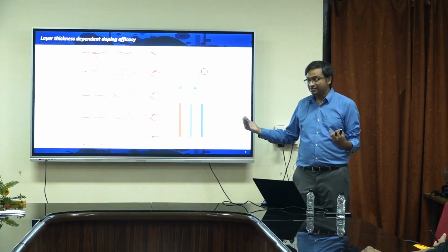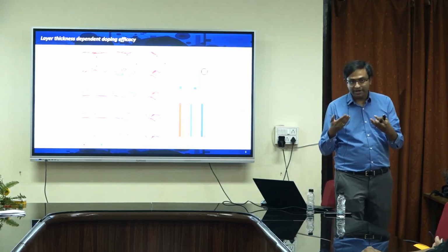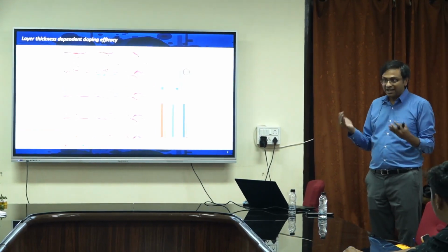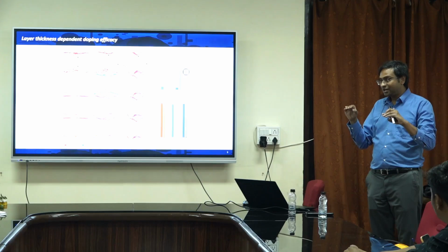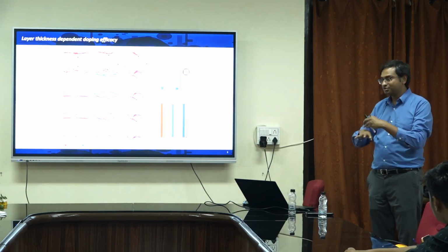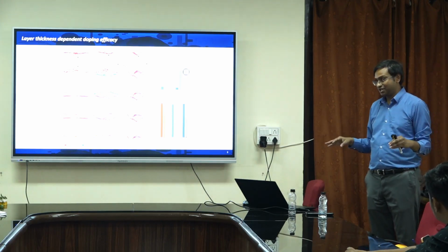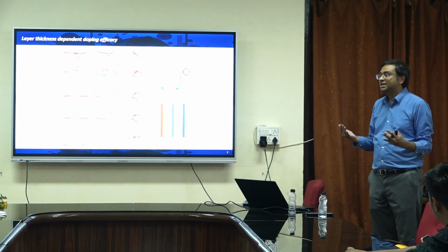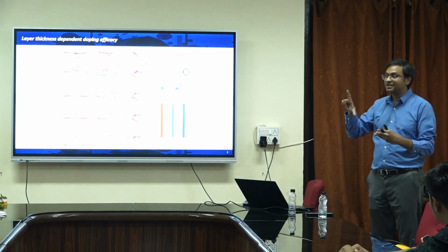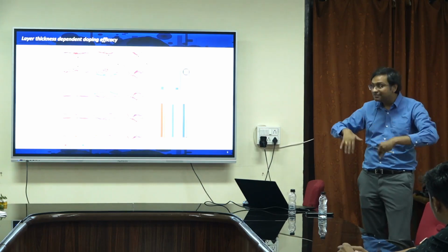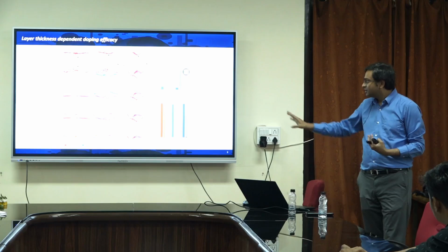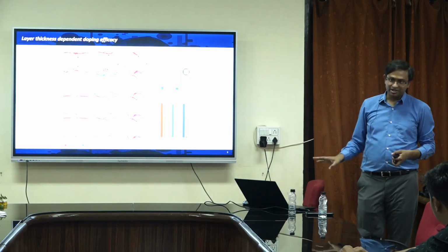So what we are seeing is that a monolayer has a larger band gap compared to the bulk layer. Whenever you introduce a dopant into a system, there is a dopant activation level, right? That is generally near the conduction band, and from there the dopant gets activated into the conduction band. If you introduce a hole-type dopant, there is an activation energy level, and it has a relative position to the conduction and valence band. For a larger band gap material, it is more difficult to activate the carriers into the conduction or valence band. Even if you don't understand, don't worry about it, okay?